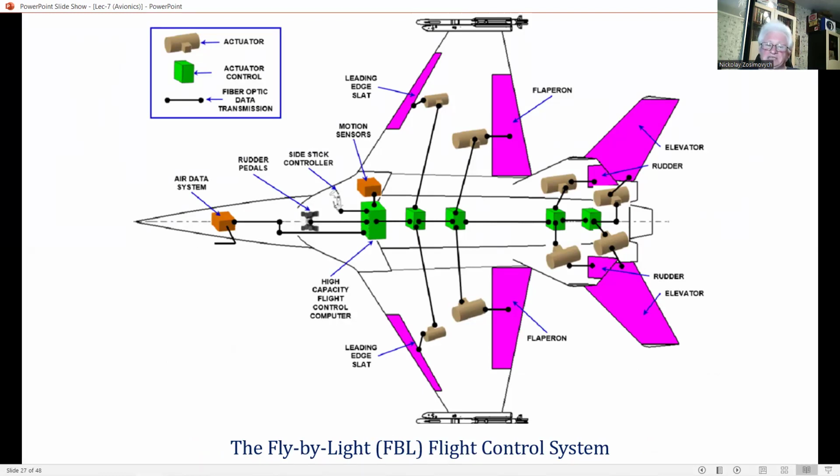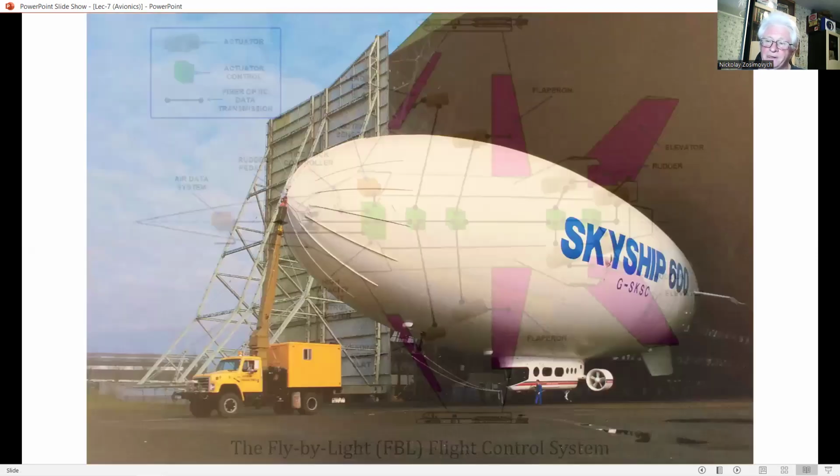The individual data channels are then recovered from the optically mixed data by passing the light signals through wavelength selective passive optical filters, which are tuned to the respective wavelengths. WDM has a very high integrity as the multiplex channels are effectively optically isolated.